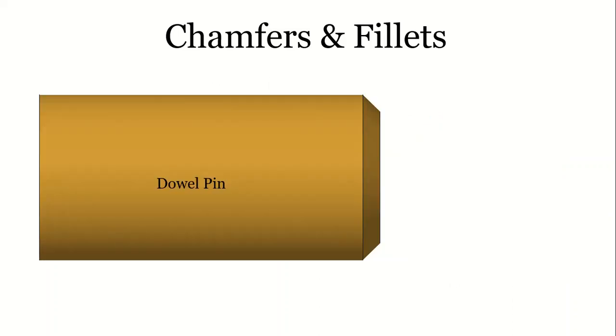So here you are seeing a dowel pin, which is basically a cylindrical part, and here you are seeing a cut on the right edge. When we want to define this cut on the right edge, you need two dimensions. Here the chamfer we are talking about is a 45-degree chamfer, and the leg length of the cut, C, is equal because it's a 45-degree chamfer. Now it is not necessary for a chamfer to be 45 degrees. It can be less as well.